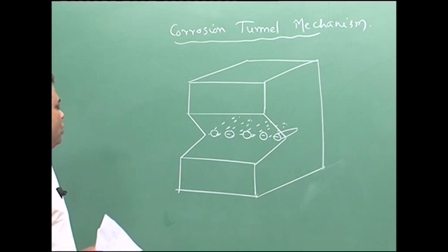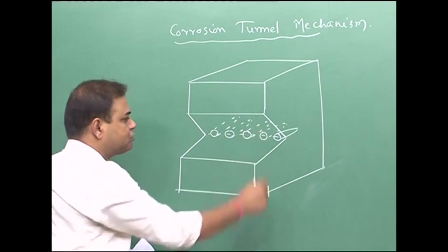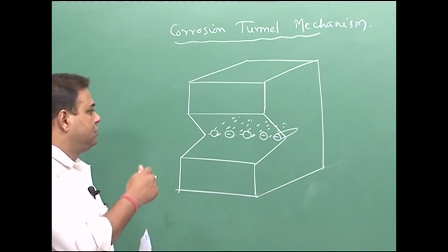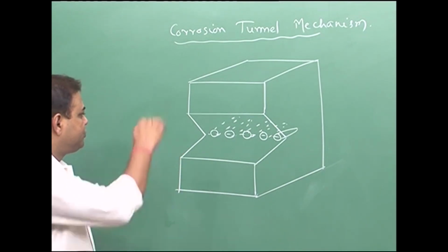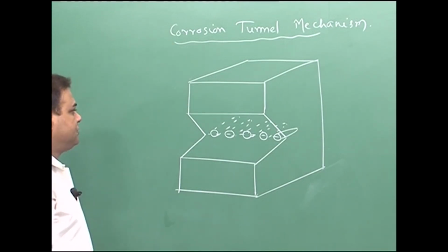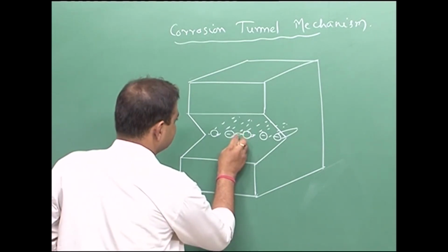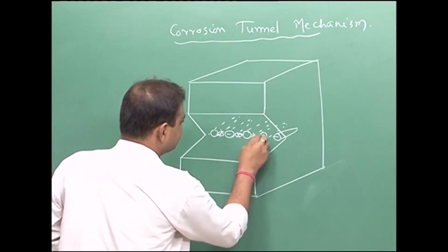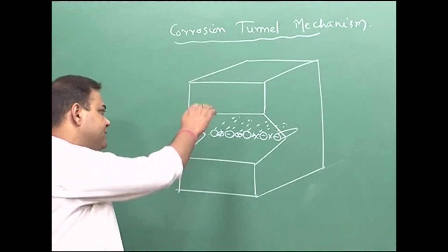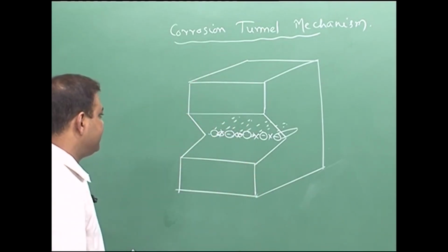There the entire load will be experienced, and due to the small cross sections of those ligaments, the stress becomes very high, and then it goes beyond the fracture stress, the UTS, and the material fails by mechanical failure mode. So in these small, unbroken ligaments, you might experience ductile failure, because the stress goes beyond UTS and then the material fails as per the mechanical failure route.